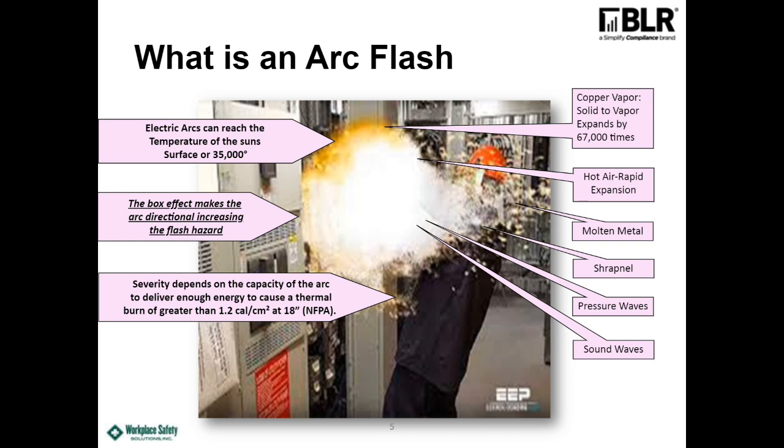In 1992, I was closing a switch in the Burlington airport, and it blew because of a dead short on the load side. And when it did, it was such a loud bang that I couldn't hear for 3 hours. And that night, I had ringing in my ears. And unfortunately, it never went away. So I have tinnitus from that one event, 1992. That was a long time ago. So hearing protection is required for doing electrical work as well.